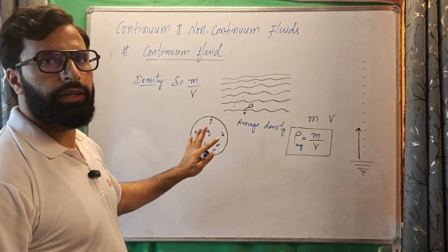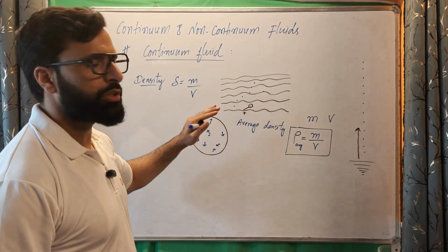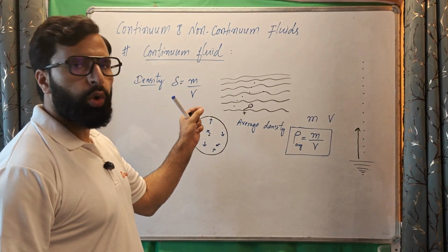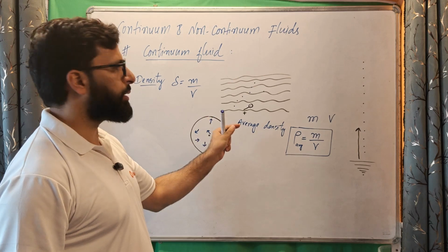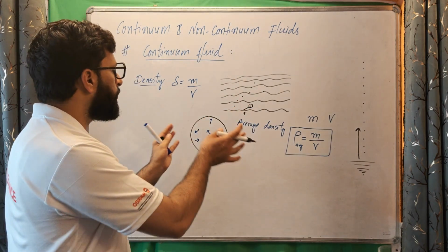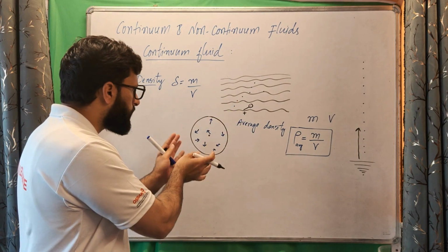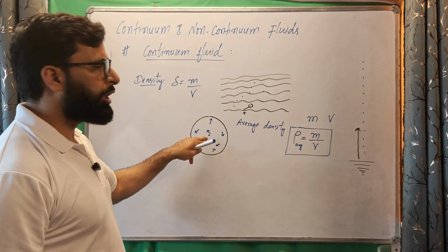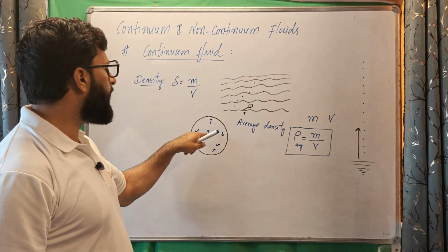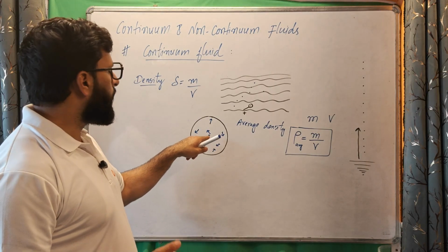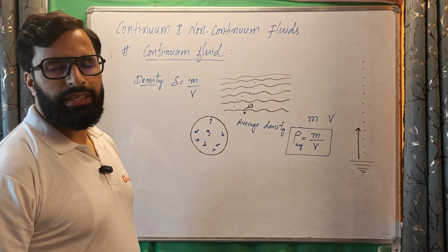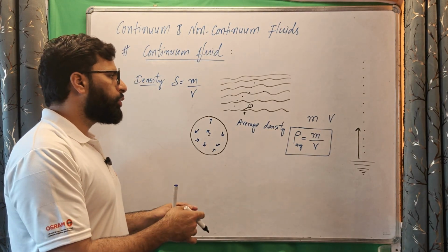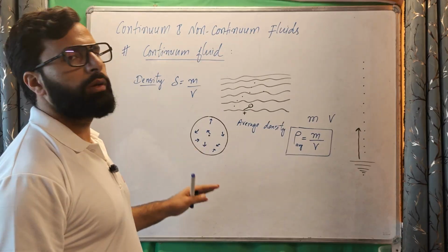First, we have to know how to define these property changes, how property changes from one point to another point. For that, we have to know what defining a property at a particular point means, and we did the exact analysis first, and we found that this is problematic. An intermolecular spacing point may end up at the empty space, and the density does not get defined and all that. Now, how to come out of this problem first?